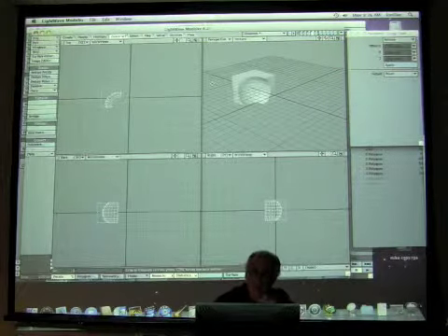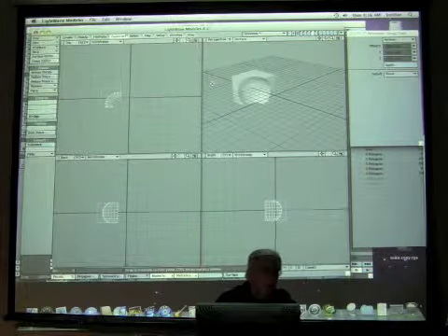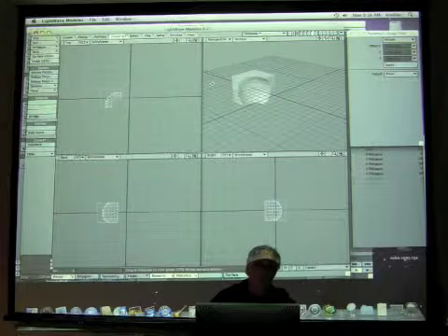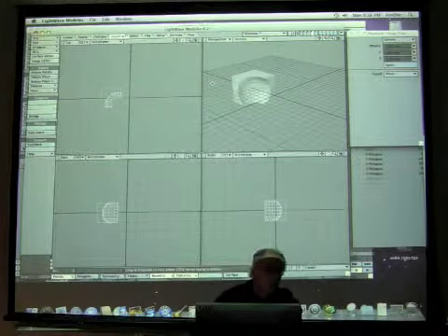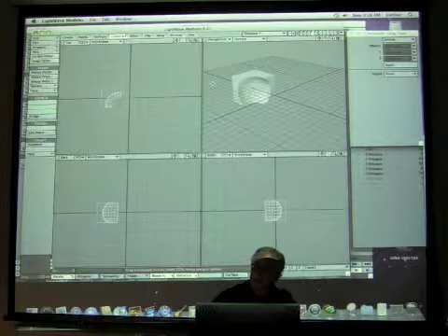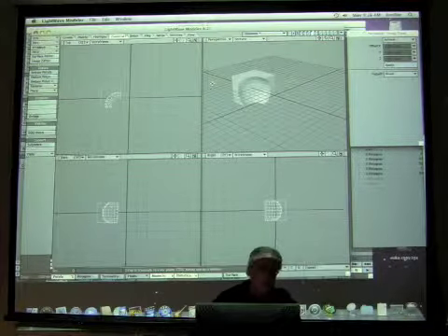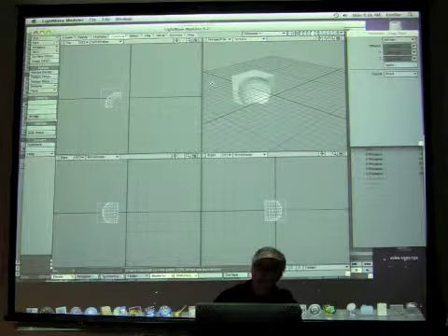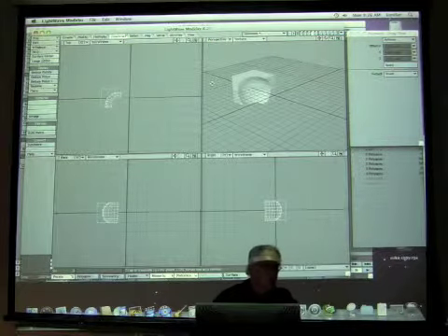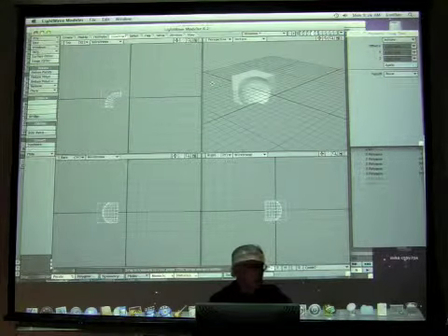And when you use Boolean modeling, where they intersect and how they combine oftentimes results in polygons that far exceed 4 points. And then you can't use that form of modeling. You might be able to do that at the very end if you wish, but if you plan on doing any organic or subpatch later on, and you use Boolean ahead of time, it won't work. There will be a conflict later on.